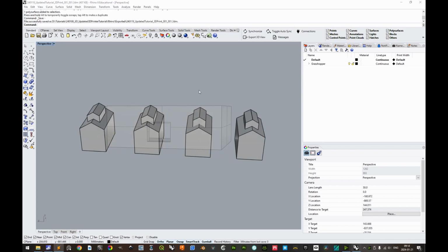The 3D Slicer software will analyze your 3D model or models and determine what is inside and what is outside for each horizontal layer. Thus, it is important that all your objects are closed and that each object's surfaces constitute a single hull or shell, so that it is totally unambiguous for the slicer software regarding what is inside and what is outside. Your object is closed when there are no openings. Your object is manifold when each individual surface has one pure inside and one pure outside.